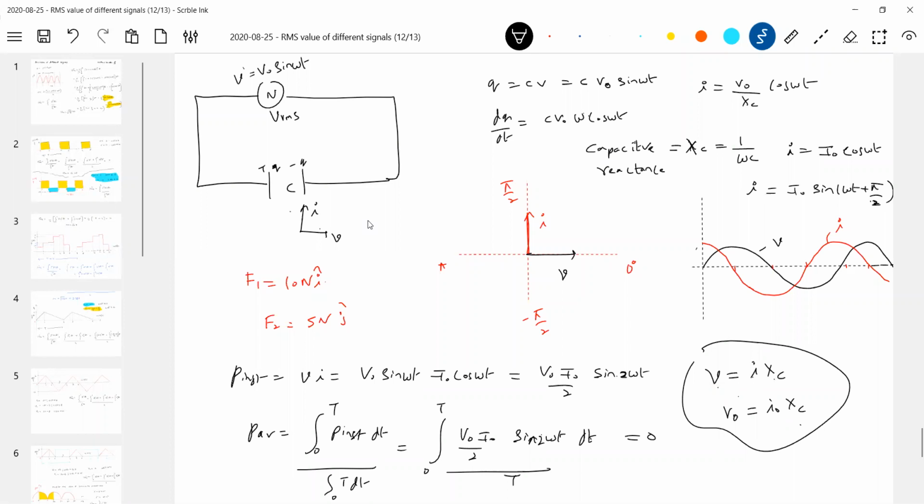So what this capacitive reactance will do is make the current lead the voltage, and it will not consume energy. So I think it's a very good element, no? The capacitor makes current lead voltage, and it will not consume any work for this. You send the same AC signal across a resistor. It will make current be in phase with the voltage, and it will dissipate power. The capacitor is bringing some changes by not consuming any power.